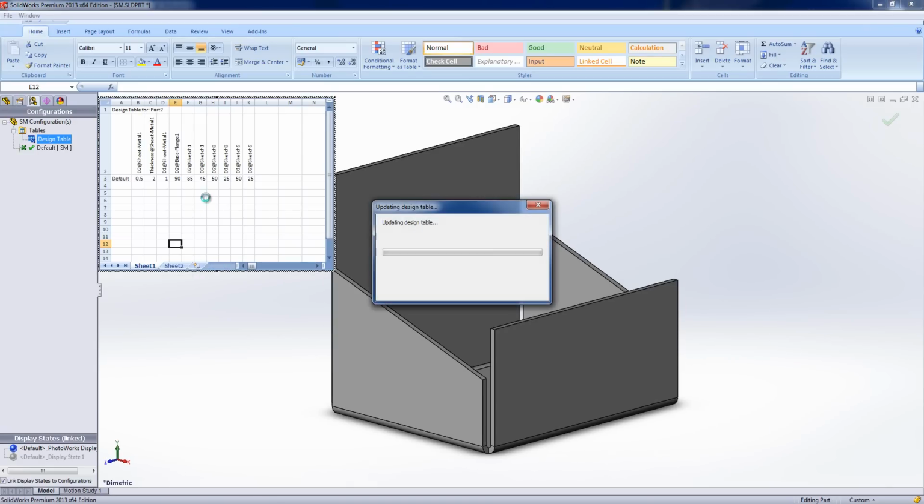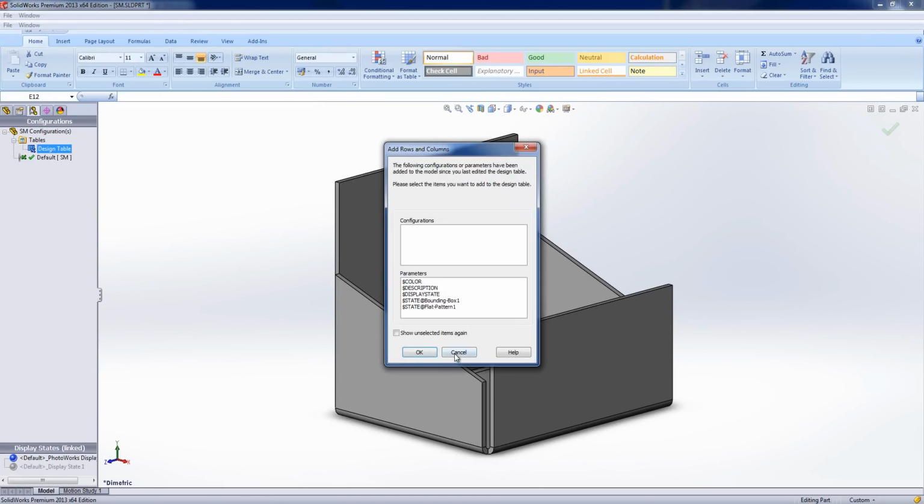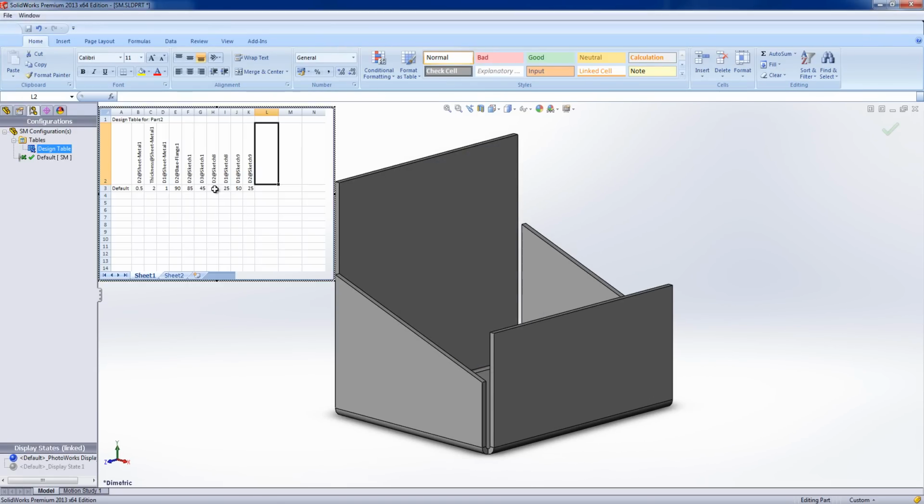So if we open that back up again, I don't want any of that. What I'm going to do is say that this equals this height minus the thickness, which I happen to know works out to the right value. So if we do that, hit return, it's now coming in as 83, and then I can do exactly the same for the next dimension as well.